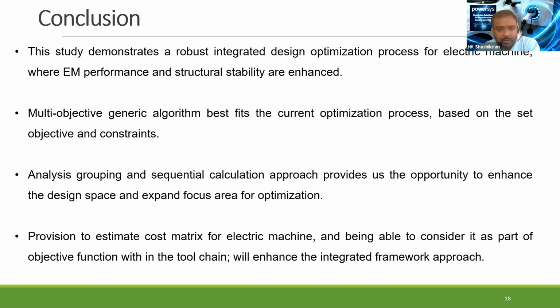Inertia is also very critical at some point because the torque that is required for our machines is very huge, so we cannot operate at very low inertia. And even for the higher inertia, we need to get to higher current levels to get the machine running at very low rpms.